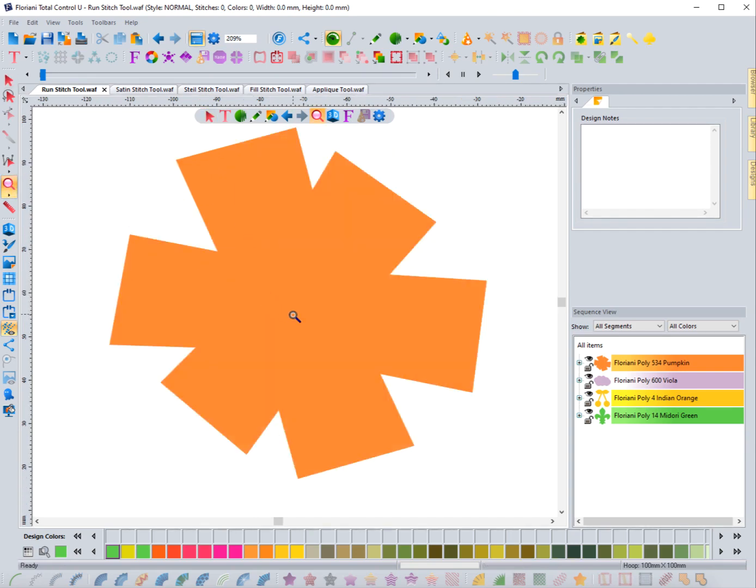In the previous video, I talked about the two different ways that you can use the digitizing tools. One where it's a standard mode, where the software will automatically put a start point, end point in for you, or an advanced mode that once you create the line and you right mouse click to generate the stitches, it gives you the option to choose the start point and end point. And I said in that video I like to work off of the standard for the most part, and so that's what digitizing mode I will be in this video.